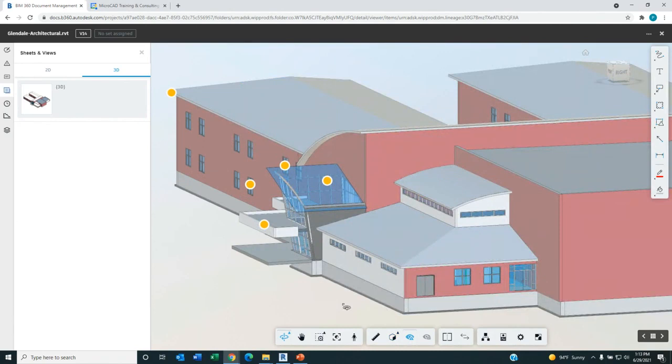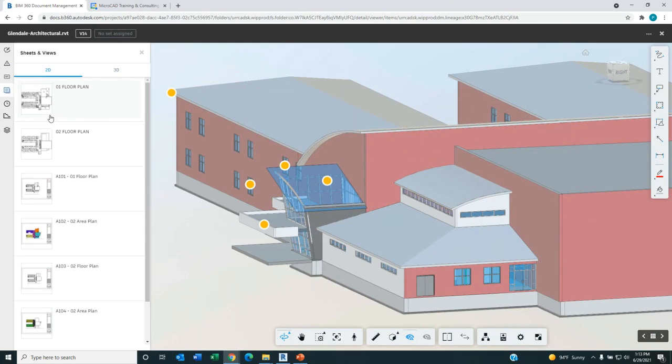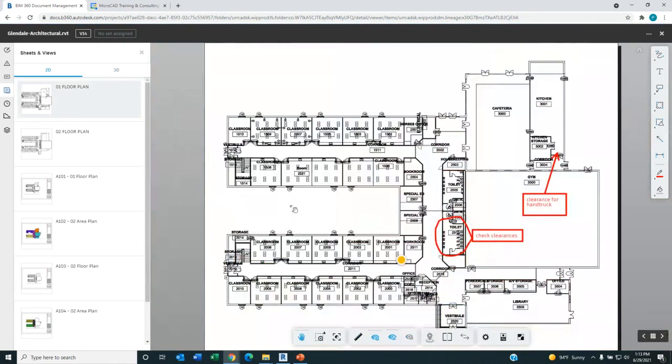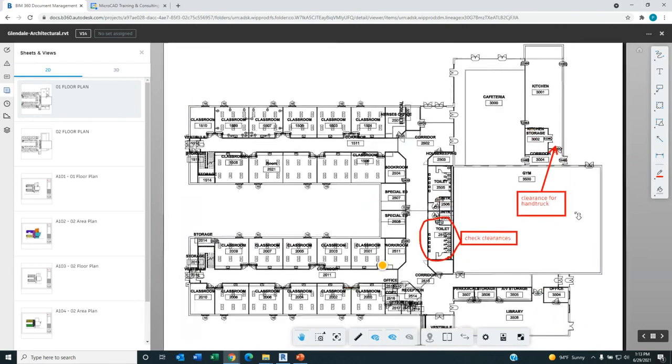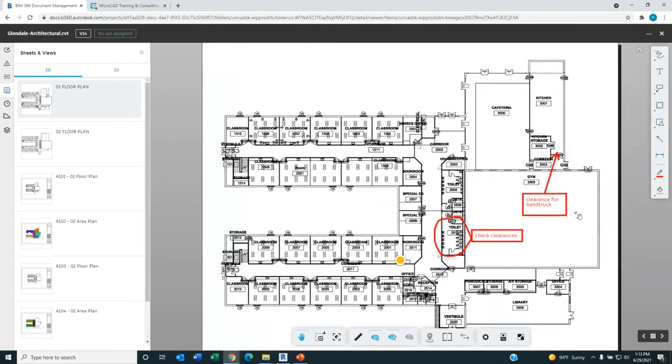As well as bringing in the 3D model, it brings in 2D drawings that were created in Revit. So if we go to one of these, it's a 2D drawing, and these 2Ds as well as the 3Ds could have redlining. So there's an entire panel of redlining functions that let you mark up bubble and cloud and giving some text, marking up, including dimensionality, the drawings for communication with other people.